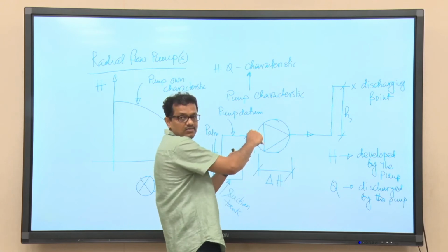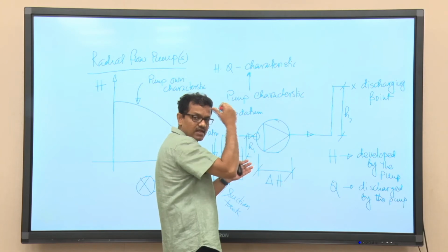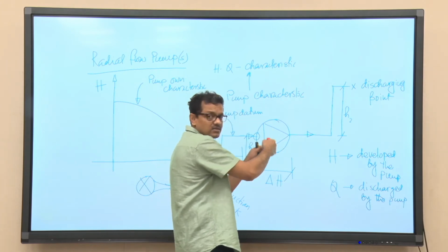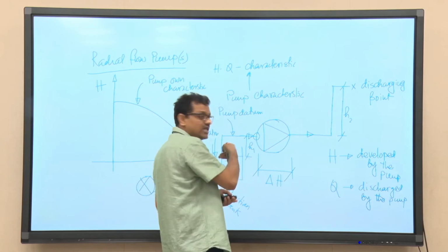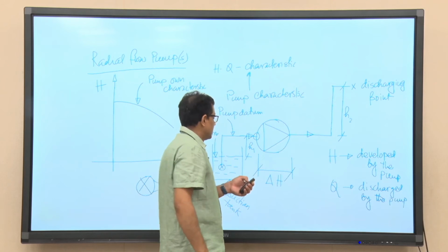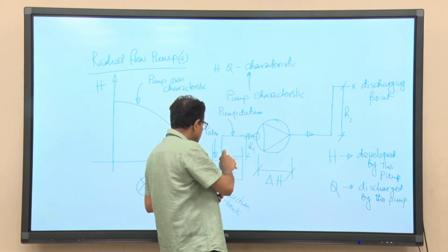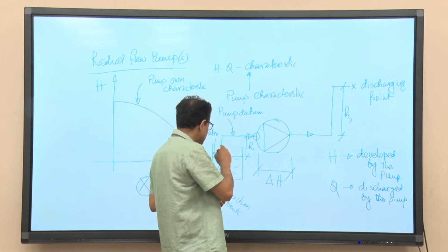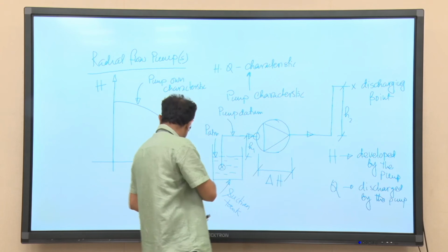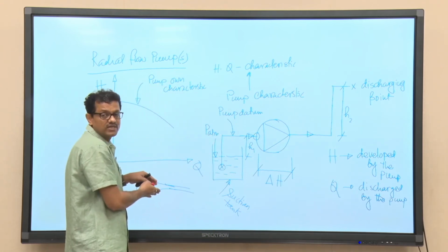to that height. For that we need to impart energy to the liquid, so the liquid will come from this point to that point. Then the friction loss while the liquid is being transported from this point to that point, plus the minor losses due to the presence of bend and also loss due to sudden contraction. So, we cannot avoid it.